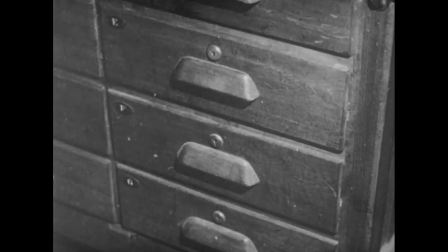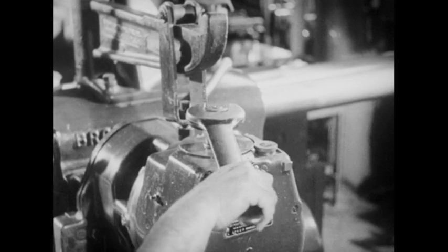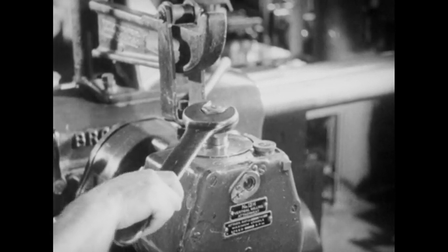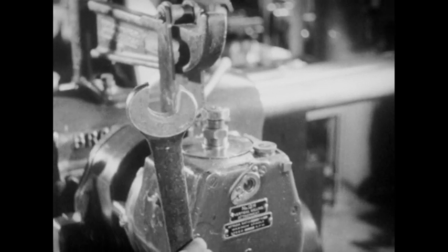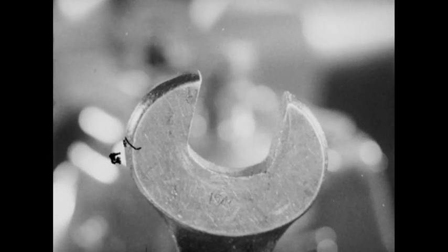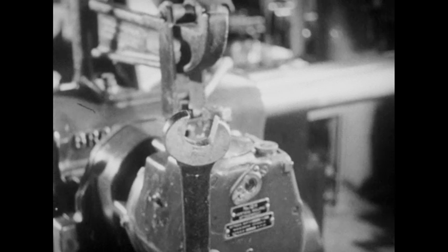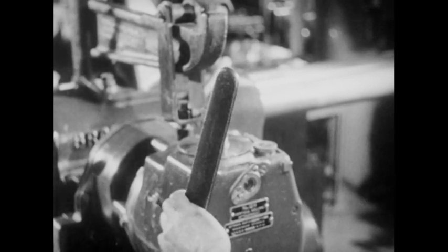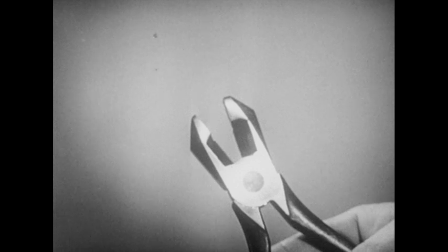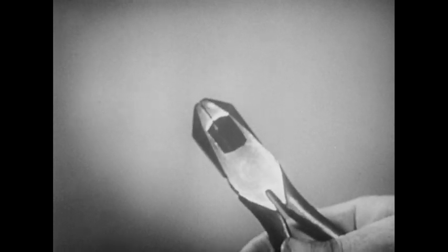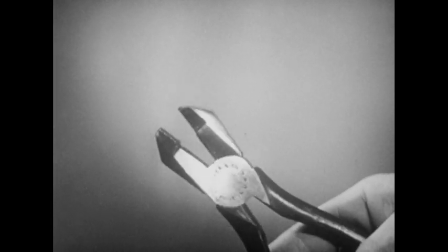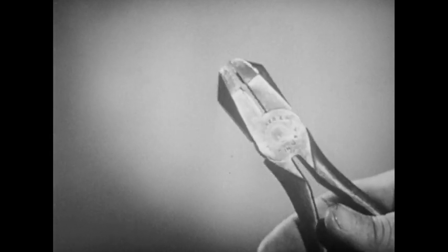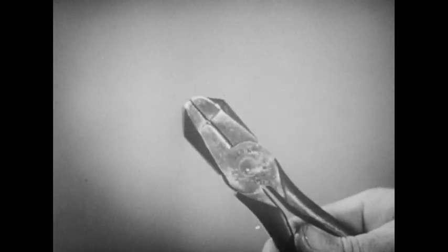In selecting dimensions, consider the function of each part and give dimensions with proper tolerances for the parts which must fit and work with other parts, such as the open end of the wrench which must fit the bolt head. Other dimensions of the wrench are not so critical. Parts which must work together, called mating parts, have highly functional requirements. The cutting edges of these blades, the hole in the blades for the pin to fit, and the pin itself must be dimensioned with closer tolerances than other parts of the pliers.